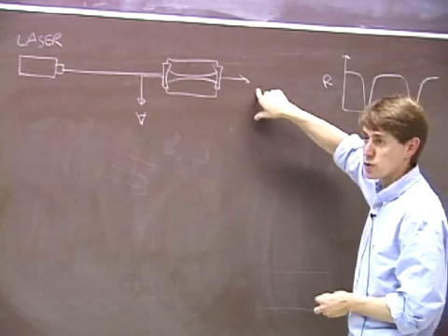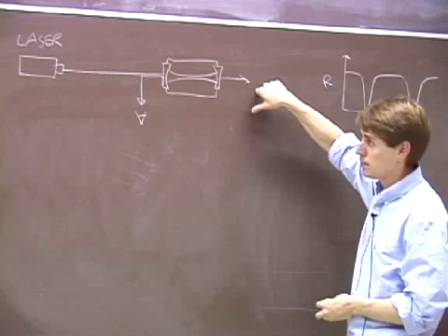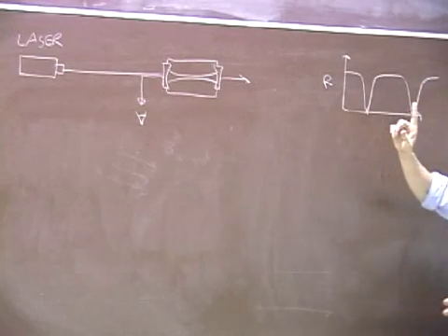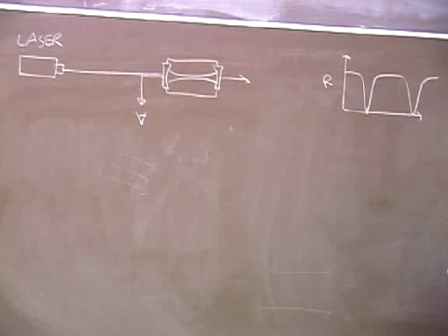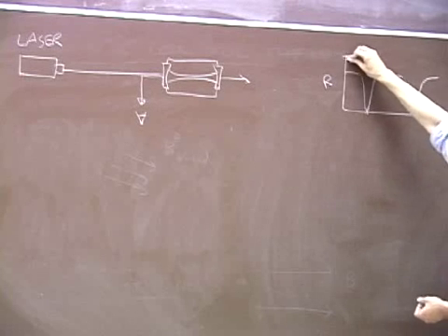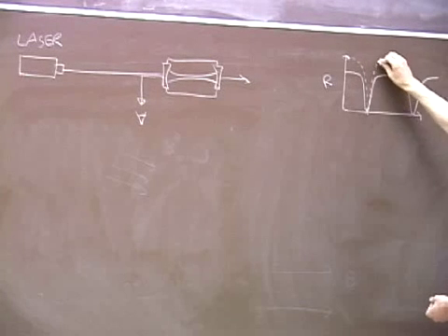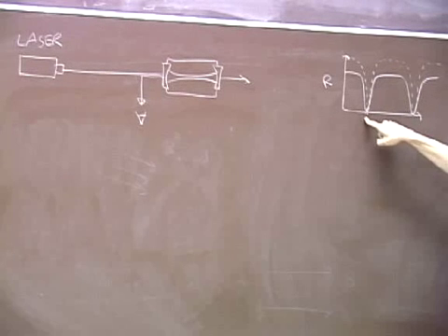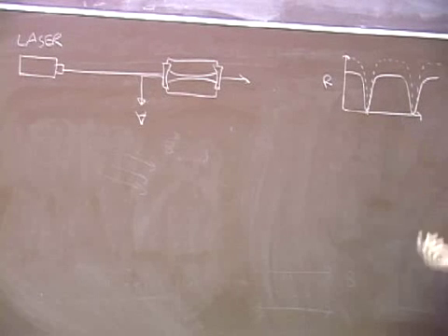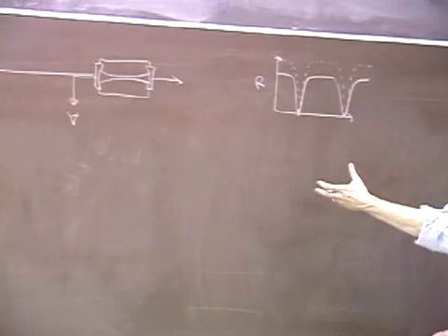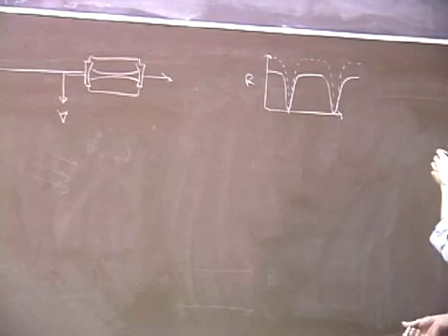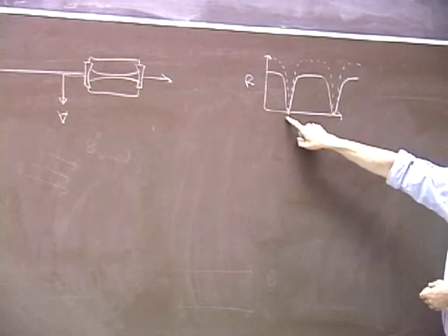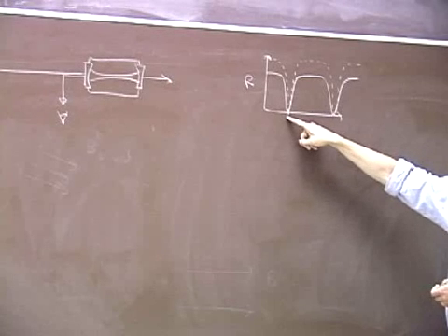We get to use all of the power of the laser in our interferometer, and we've decoupled the system from intensity fluctuations. So if we lock to 0 and the intensity of the laser fluctuates, big deal. Fluctuations in 0 are 0. So you no longer couple to intensity fluctuations. The only problem is, how do you tell the system which way to push the frequency if it changes?